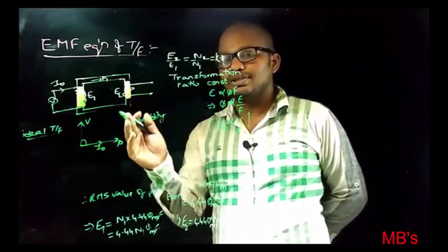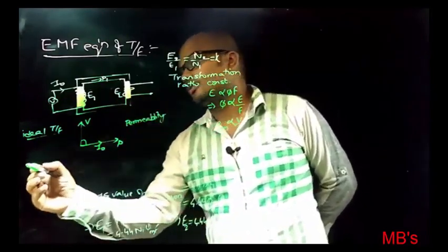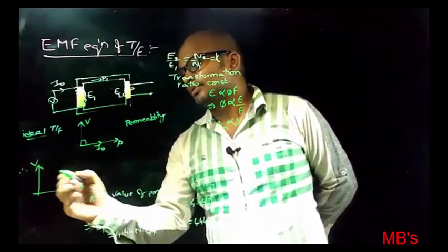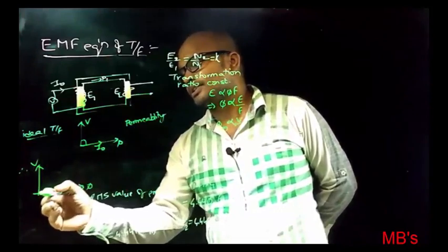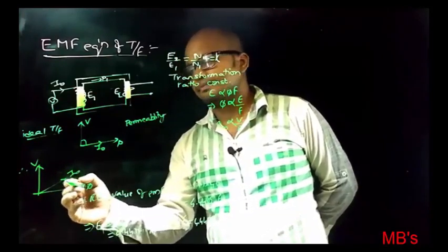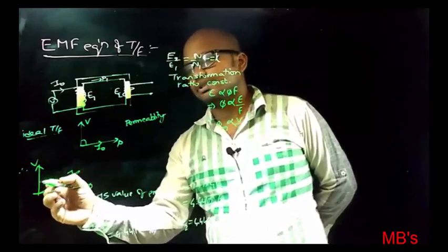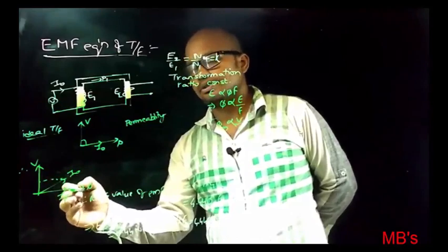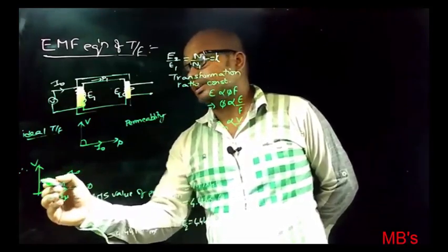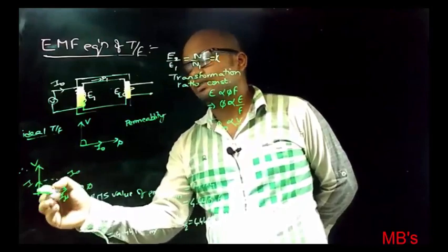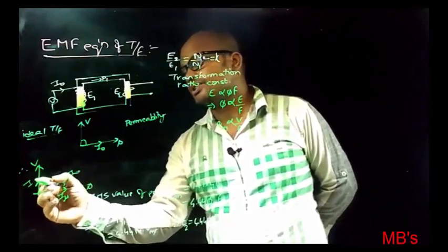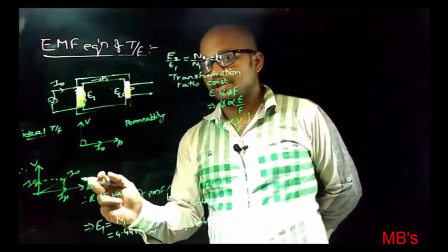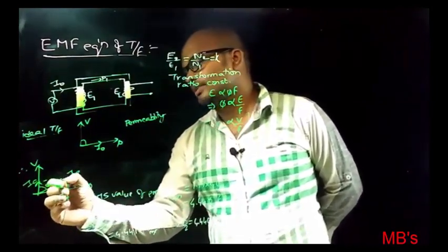But with excitation, permeability will change. Therefore, in the case of a normal transformer, V and flux will be like this and I0 will be like this. Therefore, I0 will have two components. One along the flux, which is called the magnetizing component of no load current, and the other current which is drawn along the input voltage is called Ic, which is the core loss component of no load current, and let the initial power factor angle be phi naught.